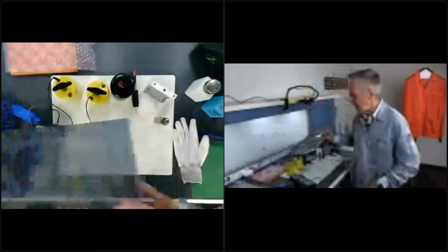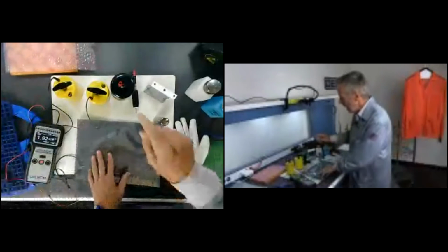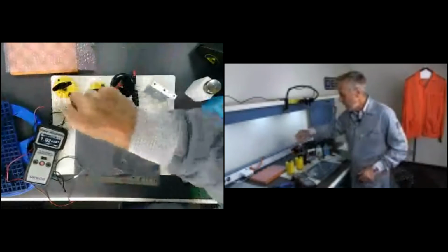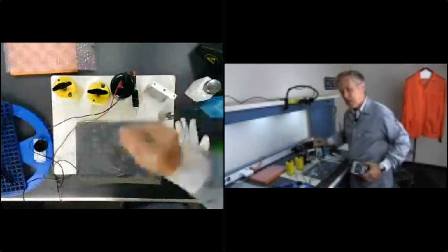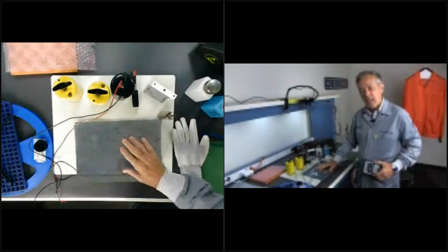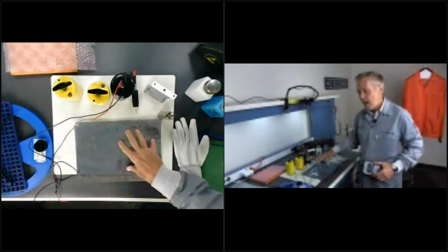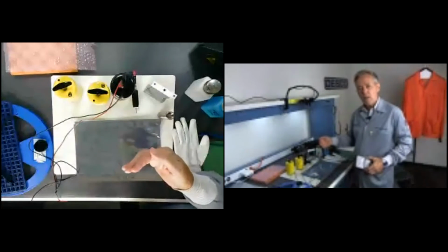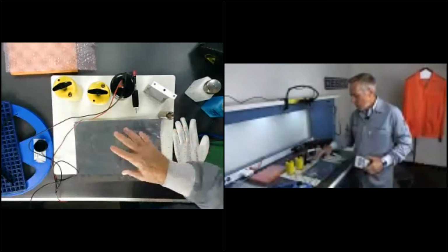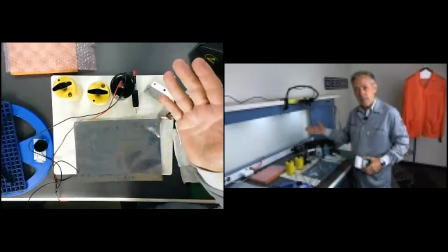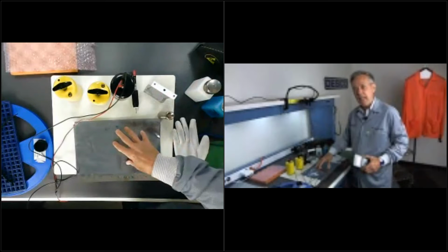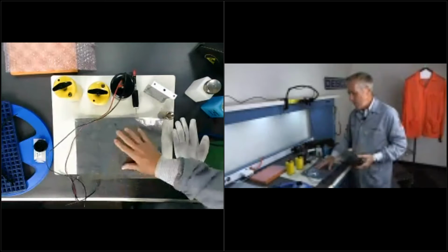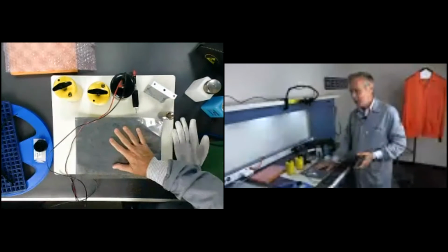So I got a static shielding bag here, common metal in static shielding bag. I'm going to switch to my concentric ring probe now, because again, I only want to know what the surface resistance of the bag is. And the reason I'm concerned about that is because resistance will and can equate to charge generation. So the reason we make static shielding bags or ESD packaging materials dissipative on the outside and inside is so when something rubs up against them, I slide a circuit board in and out, for instance, or I rub this on my clothes, that they minimize charge generation.